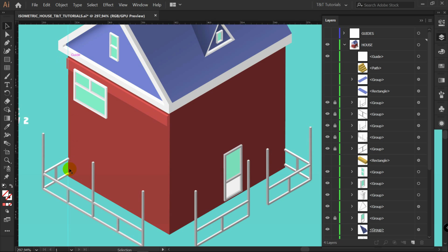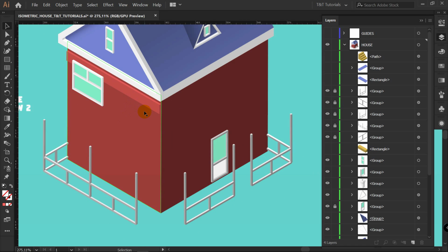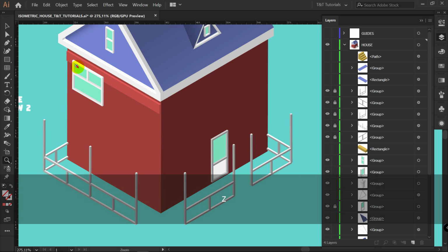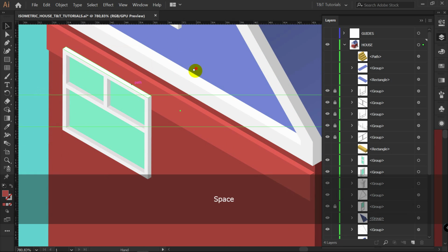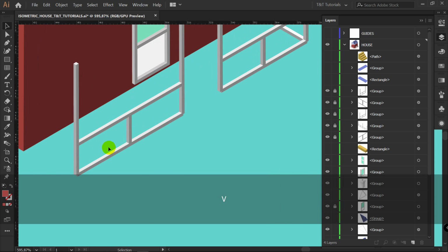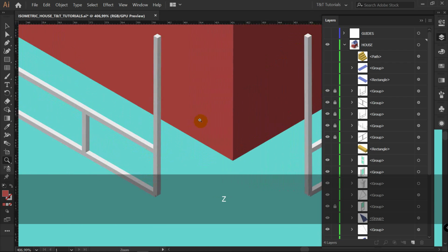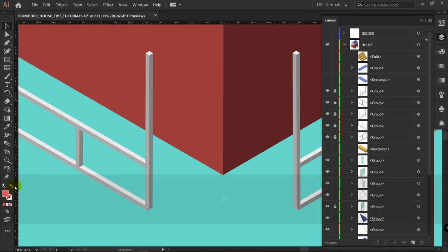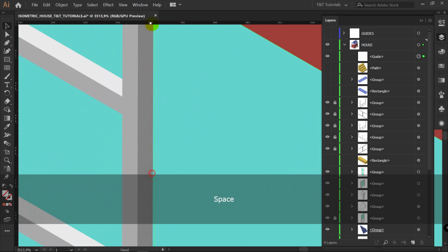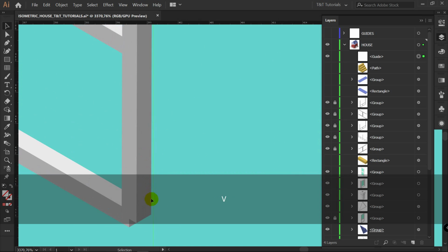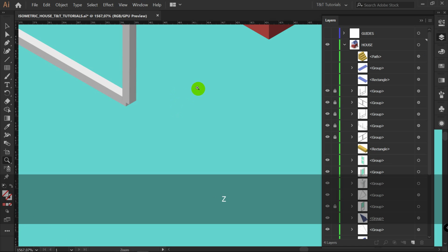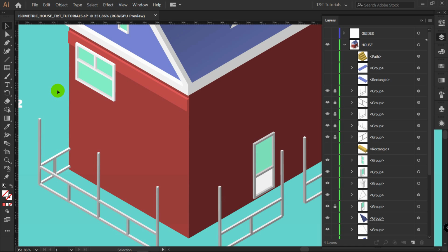Right now we will align these lines, and that doesn't mean that you should always align all lines that you have created. Only some long parts and very important parts should be aligned. So don't worry about windows, for example, such parts, and even about these parts, because when you know about distortion, you can see it very well. If you will need to remove distortion from these objects, for example, we have it here also, as you can see, this is very easy to do. You will just pick needed points and align them. But you should not do this all the time. Later you will understand which object needs to be aligned and which you can leave as they are.